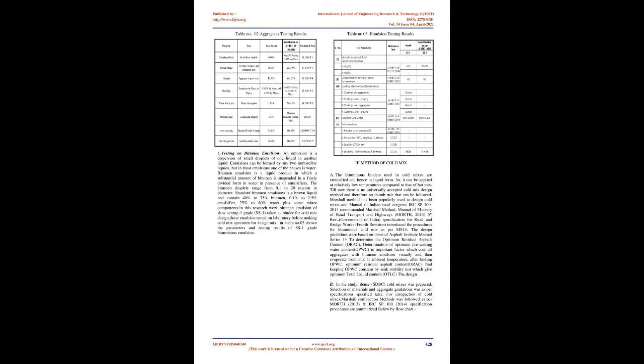Besides this, in some north and northeastern parts of India like Jammu and Kashmir, Assam, Manipur, Meghalaya, Arunachal Pradesh, and others, rural road projects involving several lakhs and crores of rupees are beyond time. Due to topographical and weather constraints, it is difficult to work with hot mix technology in such hilly regions, heavy rainfall, and forest zones. So, it is desirable to find a suitable alternative for hot mix technology. This alternative falls in cold mix technology.